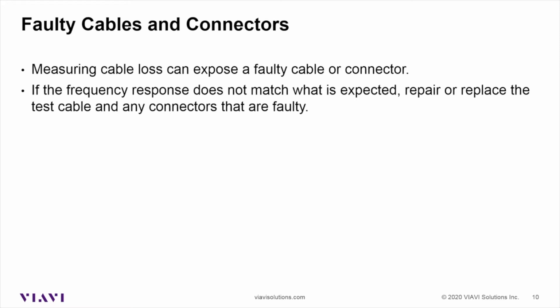But what that doesn't tell us is whether the cable we have in our hands is actually good. So even if you're able to look these things up, it's still a good idea to go through and characterize the cables you have, the attenuators you have, make sure that the connectors you have are good.